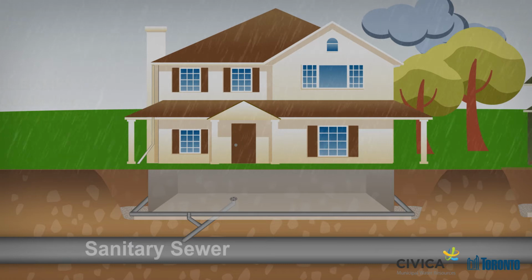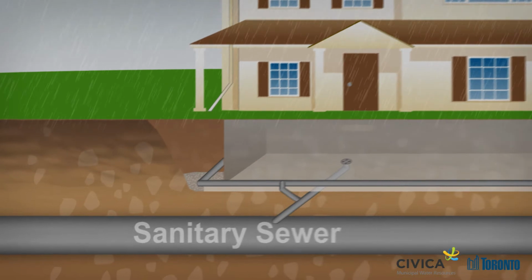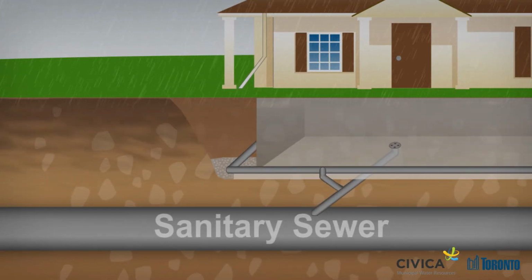Using the results from the October 28th investigation to pinpoint problem areas, a second CCTV pipe inspection was completed on August 16, 2016. This time with a focus on the sanitary service laterals from the houses to the street. The intent of these inspections was to distinguish between I&I contributions from possible defects in the service lateral pipes and water coming from the foundation drains.